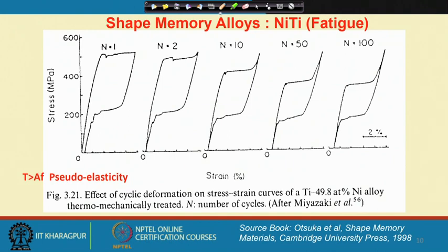Now, this is a very different aspect of shape memory alloy, where we need to think about the effect of thermal cycle. We already know about the transformation sequence and the stress sequence. In the austenite phase field, if I apply some stress and pseudo elasticity exists, then after unloading all the martensite transforms into austenite. How does the curve basically look?